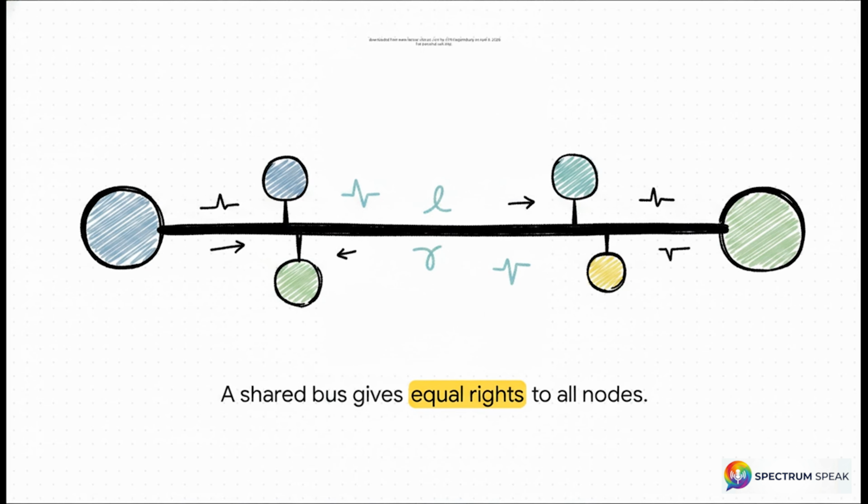Now, this brilliantly illustrates a CAN cluster. When you connect all of these distinct corporate offices together over a shared physical wire, they form a strict bus topology. And what's really fascinating here is that in a CAN network, every single node has totally equal rights to the bus. There's no giant central master node controlling everything. Any node can transmit data whenever the bus is free.